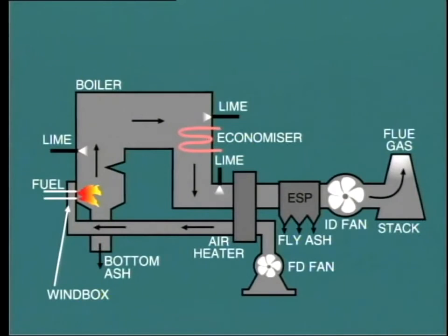In the dry method, the lime as a fine dust is blown into the flue gas stream at various injection points. The particles of lime pass along with the flue gas and attach themselves to the fly ash. Reaction with the SO2 takes place to form calcium sulfite, and this solid particulate is captured along with the fly ash in the precipitator or baghouse filter. Although this system is relatively simple, its absorption process is not very efficient, so the consumption of reagent lime is extremely high. However, this system may be utilized on small boilers if the target for SO2 removal is limited to about 60%.